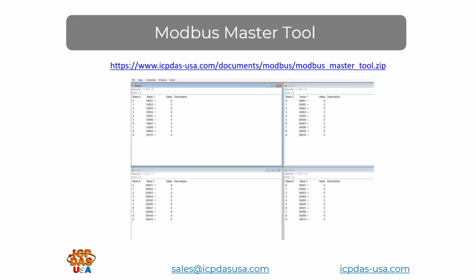This is shown here. Our Modbus Master Tool is a free utility we provide for Windows PCs. If you have one of our TM7561, the i7561U, or any third-party RS-232 or 485 converter, you can connect your PC in place of the Modbus Master and test communication to your slave devices. You can read data in engineering, hex, or float format to help debug and simulate your application. Later, we will discuss scaling.